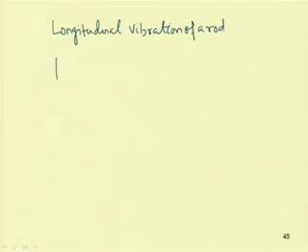In this case, this is the rod, let us take a cantilever type. We are supposed to find the vibration of this rod. So, let us take a small element in this rod at a distance x, and let its displacement be u. We are taking a very small element which is dx.